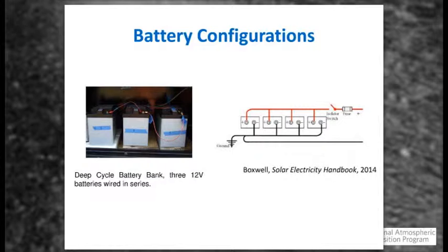Just a bit that we highlighted at first, some safety things. We do recommend an inline switch so that you can disconnect them. Yes, this is low voltage, it's easy to handle, but those batteries have an appreciable capacity. If you get a short, you will quickly melt wiring. You could even quickly have a small electrical fire. So even though it's 12 volts and you think it's safe to handle, you would want some kind of inline fuse in case of shorting. And along the red line, you can see to the right, fusing. And then we would recommend grounding of the negative side. That would be for general equipment protection and also protection if there was a lightning strike. Next slide, please.